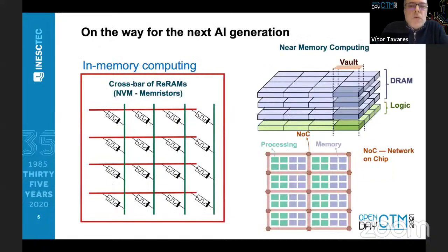So one way to move forward in terms of hardware architectures for the future AI: there is a lot of research on ways to address the problem of memory bandwidth, so the time that it takes to address the memory, put data there and retrieve data from there. The best way is to actually bring memory close to the processing side. One of the things that has been proposed, and people are working on this, is to stack layers of chips that will be dynamic RAMs.